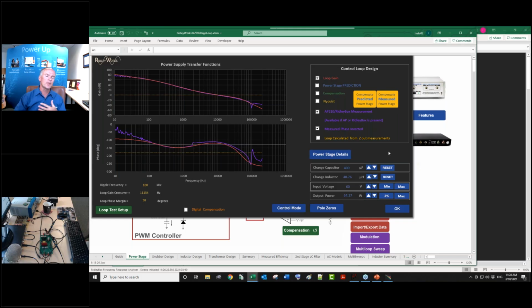If everything were a simple first order buck converter type thing with no non-minimum phase, then that would be the only place you could use a loop gain. But yeah, non-minimum phase systems are just fine. I'm sure when Bode did his original systems, I know what you're asking. It says in the textbook that if it's a non-minimum phase system, like with a right half plane zero in it, it's wrong. And quite honestly, that should be struck from control books.